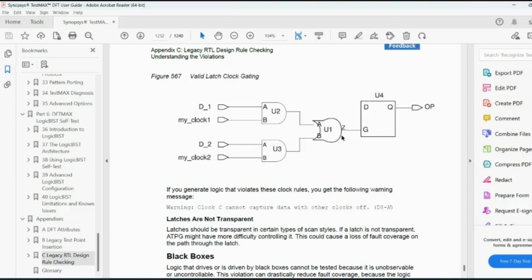But in practicality, you will not face this kind of differential clock scenario. This is a design issue, and we will inform the RTL team to maintain synchronicity across the entire design by having the same type of clock gating cell environment. Even DFT engineers can fix it, or you can ask the RTL team to fix it. How the DFT fix works, we will discuss later. Okay.